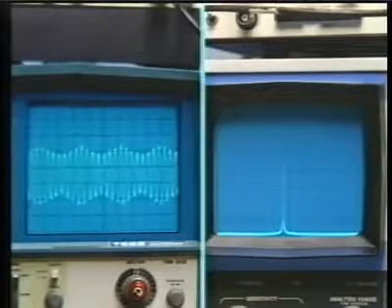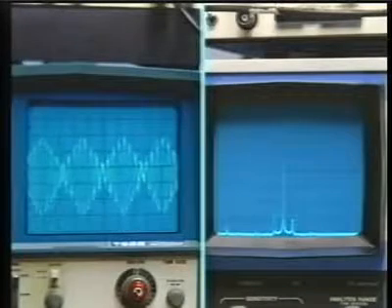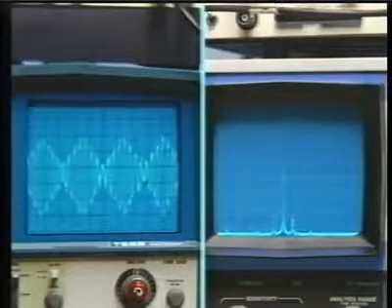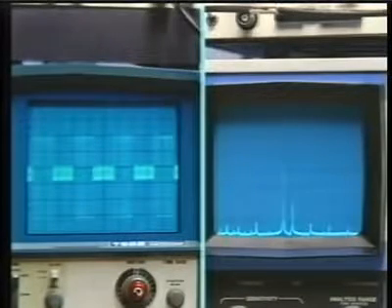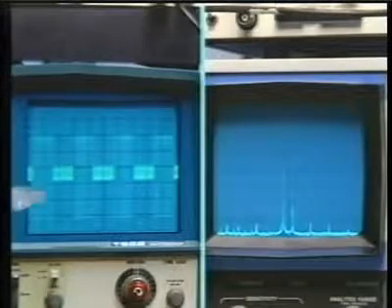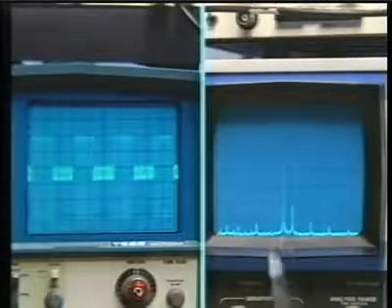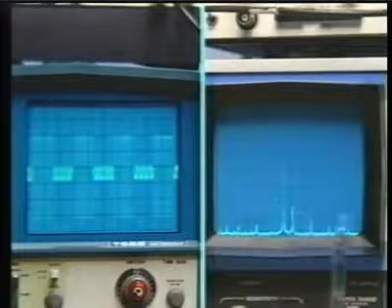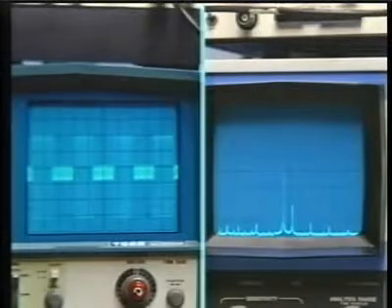As I bring them back in, again, this is triangular. There would be harmonics there that maybe are a little hard to see in the spectrum analyzer. I'll go back first to a square wave modulating signal, and you can see the square wave on top and one on the bottom. And so all of this then represents sidebands, is that? That's right. Those are the sidebands due to the square wave modulation.